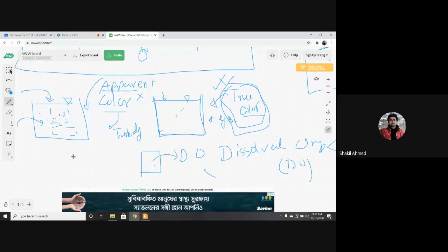That's why in an aquarium you sometimes use bubbles to aerate it. Applying air means applying oxygen, so that the DO is greater than or equal to 4 milligrams per liter. If it's less than this, the fish will die. Am I clear?